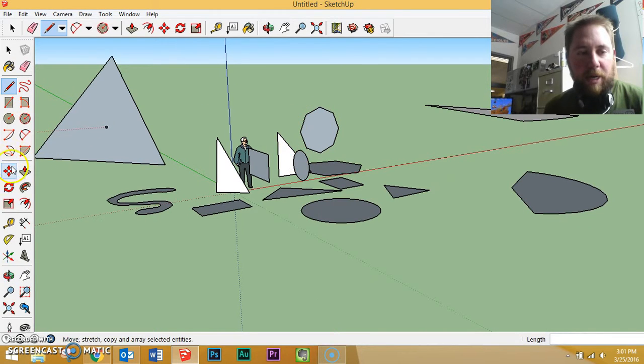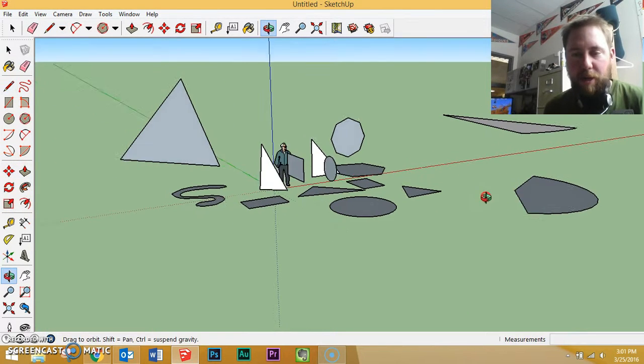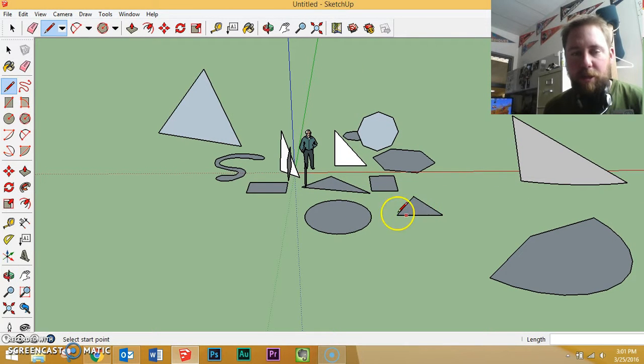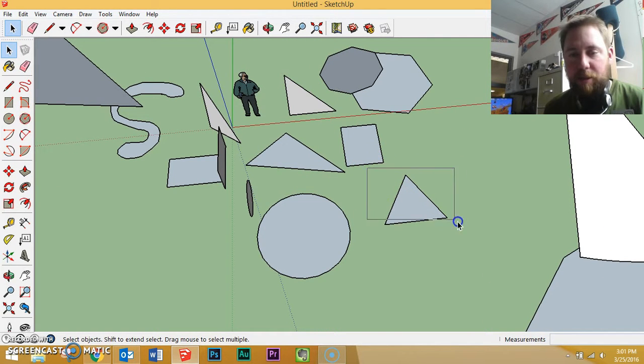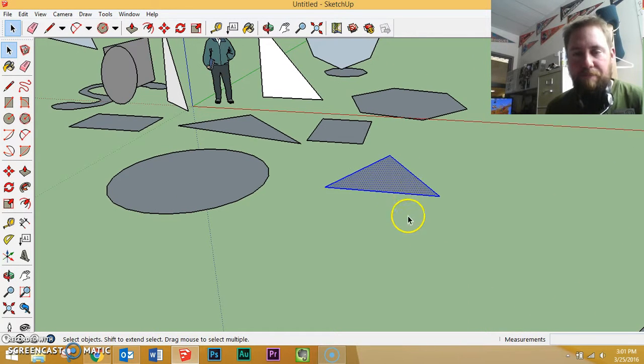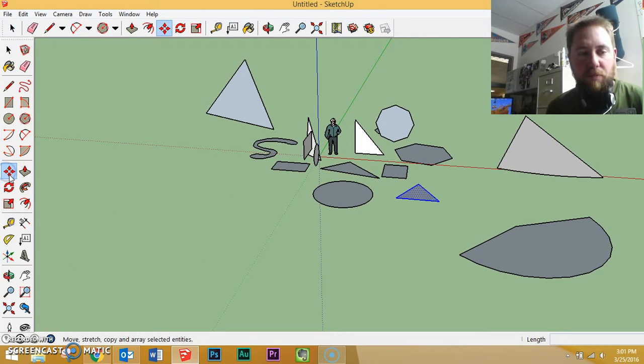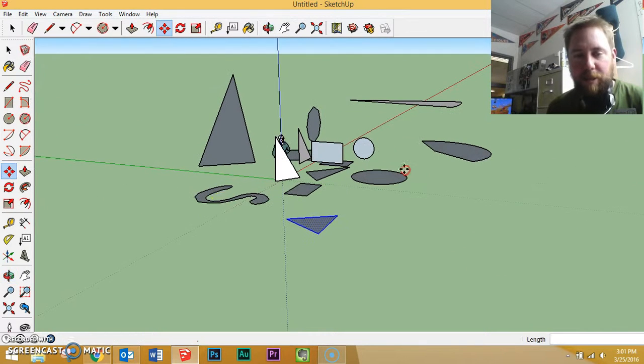Alright, so those are kind of my shape tools, really helpful. I'm going to come back in here, and now we're going to get into manipulating those shapes and doing things with them. The first one is to move a shape around. So let's say I want to move this triangle right here somewhere else. First thing I need to do is get that triangle selected. So I can either click and drag around it, make sure you're on your cursor tool up here, or I can kind of double click it right there and see how it's selected. Now I can move it. Using our move tool right here, I can now come grab it and pull it around and take it somewhere else. Okay. While I have this here, I can also use my rotation tool if I wanted to rotate it.